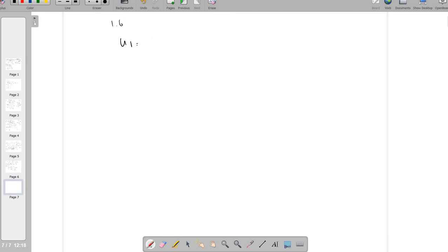I can write this equation first: 1.64 u1 minus 0.48 u2 equal to 0. So I am bringing this term to the right side. So 1.64 u1 is equal to 0.48 into minus 1.952. So u1 is equal to minus 0.5713 mm. So now the displacements u1 and u2 are found out.